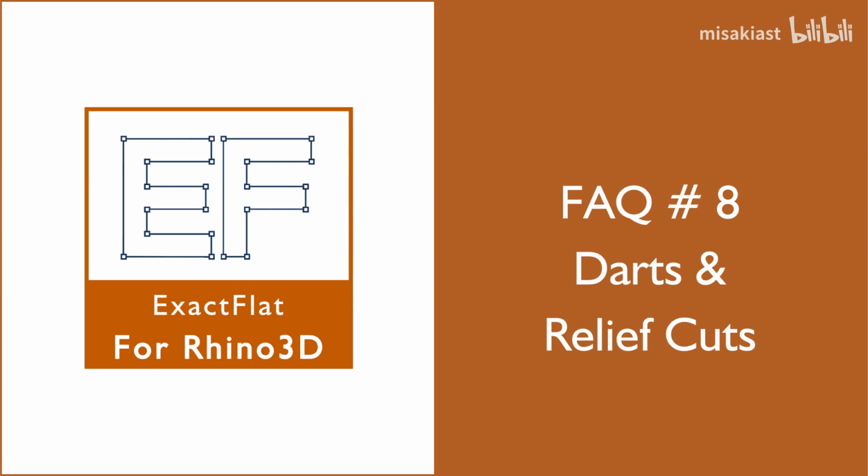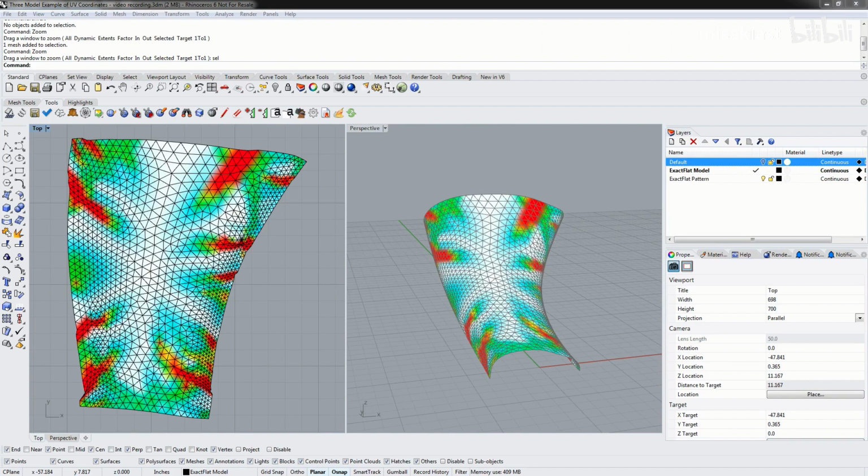Hello everyone, in this video we will talk about relief cuts and darts. Today I will show you how to use Exact Flat's shortest path cutter, the plane cutter, and the curve cutter, and I will also show you how to use some of Rhino's cutting tools to create cuts in your mesh before flattening.